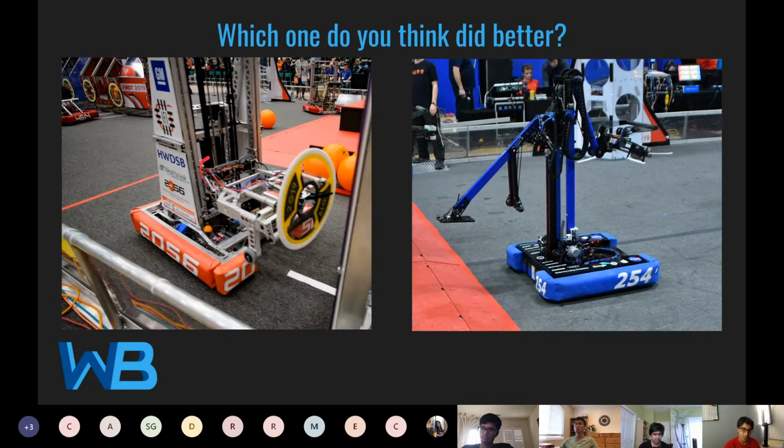How many rotary joints does it take from deployment to end function, right? Here we have one, and it's just for deployment. We also have a prismatic joint for our elevator, so 2 joints in total before we get to our end effector. Whereas on this robot, 254, we have a turret down here.